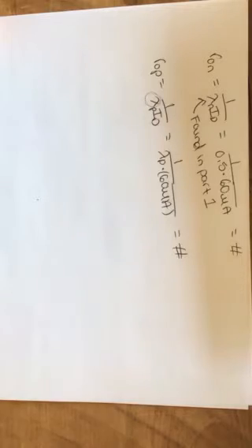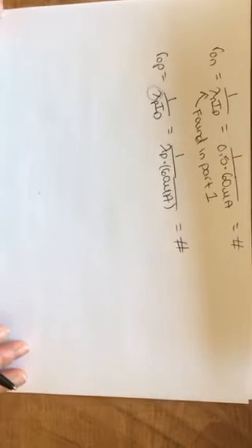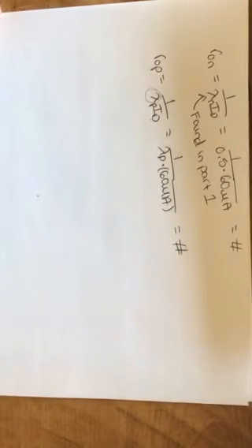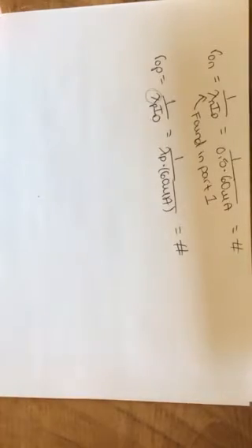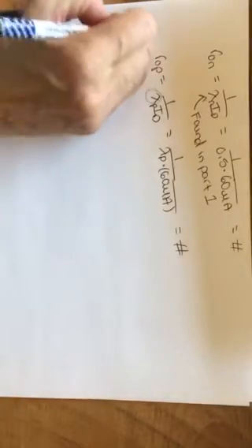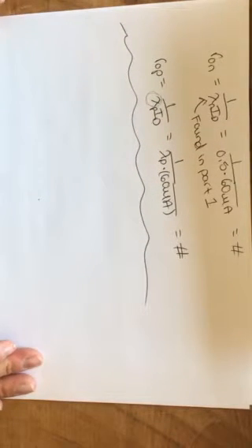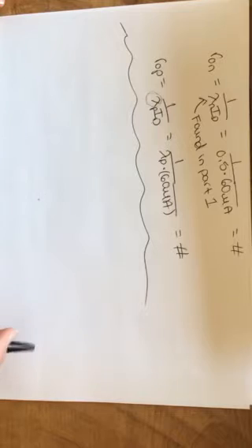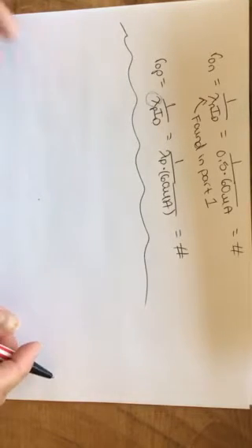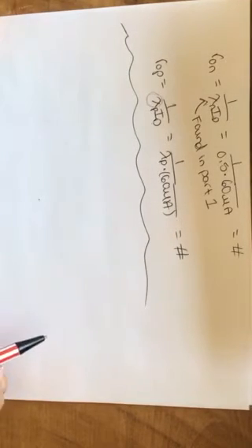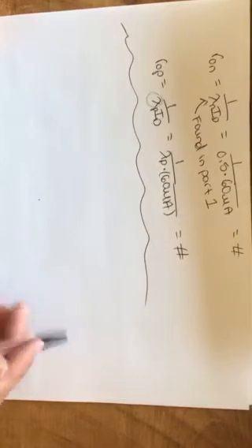In order to find the small signal gain, which is a part of our hand analysis, we are going to need our small signal model. We have set our devices to be in saturation, and we know that by our DC bias. We can calculate the r naughts and the gms, which are always our first step of any small signal hand analysis. Then we take all of our transistors and replace them with their small signal model. We only have 2 transistors, the NMOS and PMOS.